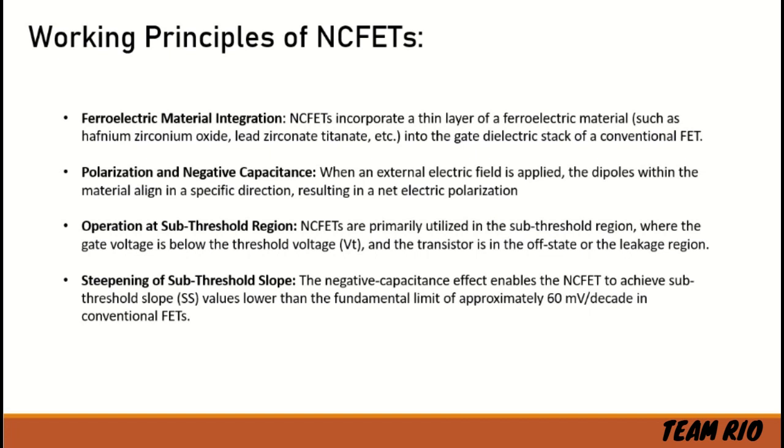Next, operation at subthreshold region. NCFETs are primarily utilized in the subthreshold region, where the gate voltage is below the threshold voltage and the transistor is in the off state or the leakage region.